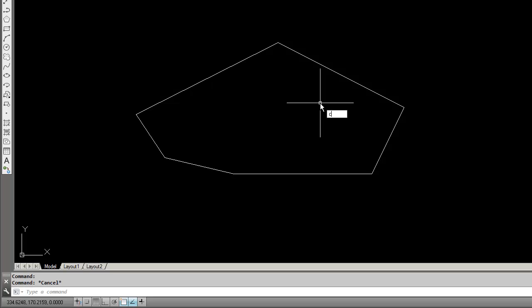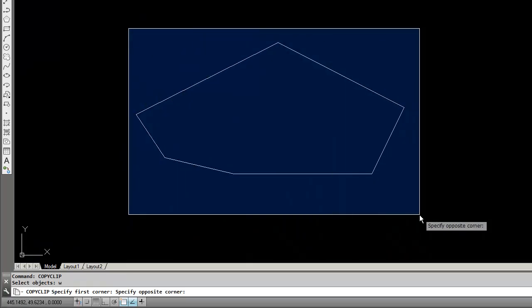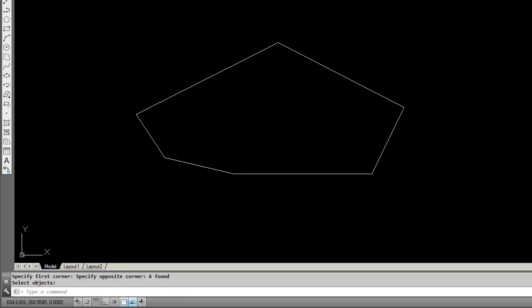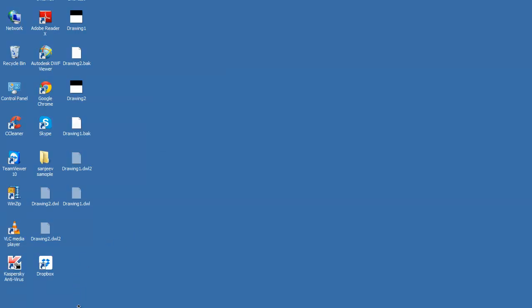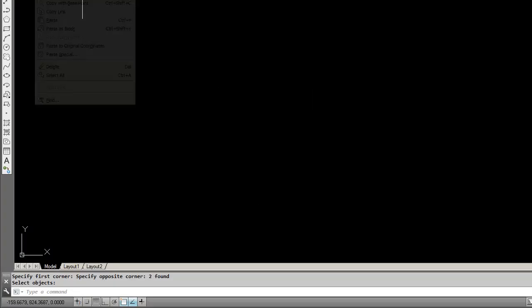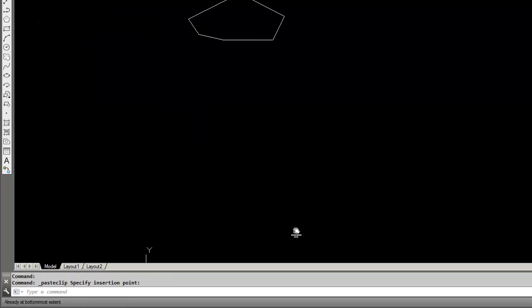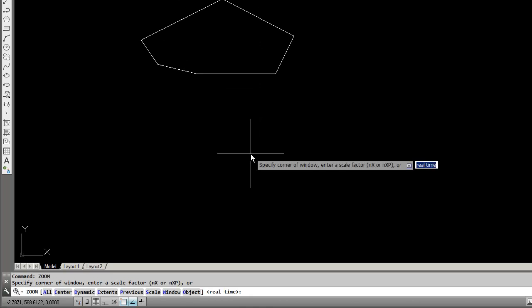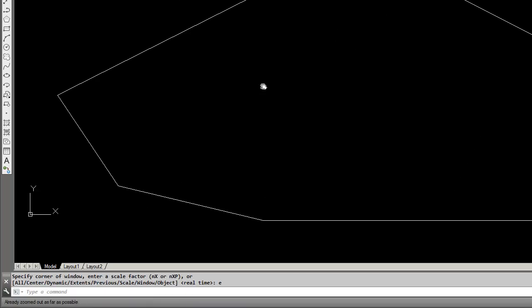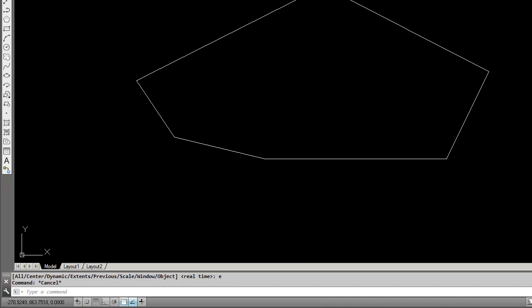So this I want to copy, let us say. You click copy, with the command, you have to type it. You press return. Then you open the other drawing, drawing 1, and you paste. It is pasted as a drawing. Okay. Suppose you want to paste as a block. See here, I will show you. This is an independent line. This is as it is pasted.